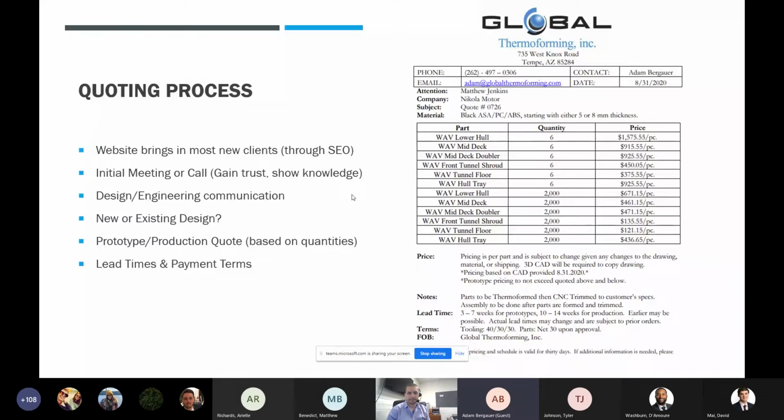So an example from start to finish: when we receive plastic, that plastic is both counted and checked to make sure that the quantity is right, the texture is right, the color is right, basically everything. We have one person in our plant that does that all day. Then it's labeled with the customer, the part number, the right rev, making sure everything's on there. Then it goes into our production schedule, and from there it's formed, cut, trimmed, and assembled or painted.